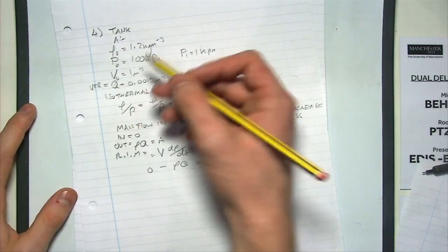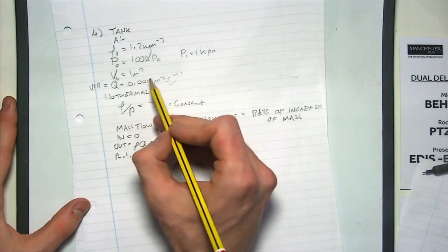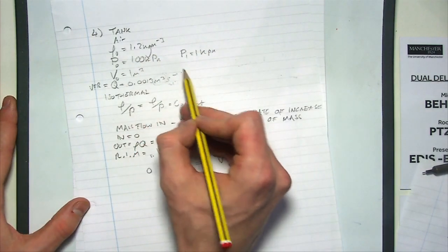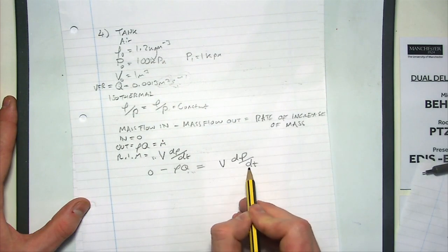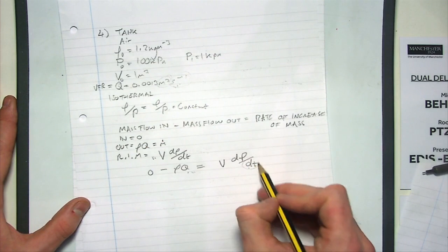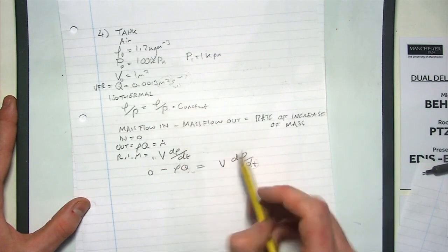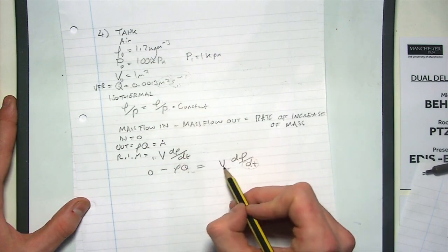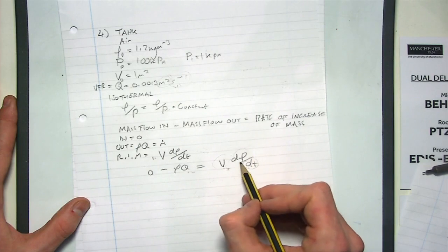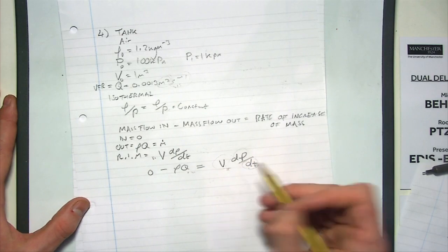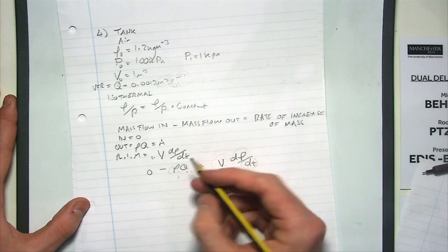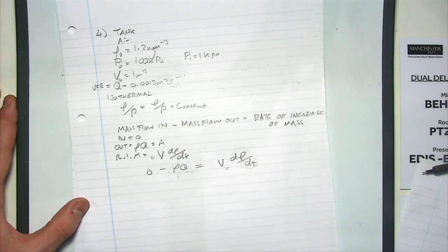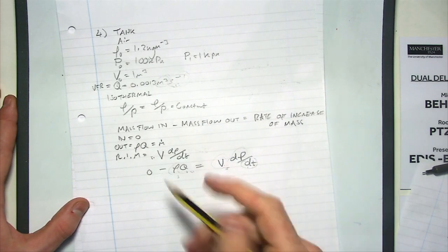But that's what that volumetric flow rate is. It's amount of volume per time. Look at the units. This has time in it, and this is with respect to time, and therefore it gets the time units in it. And because this is underneath, that gives us an s^-1 as well. So you can see how these balance. If you times the volume by this, you're left with kilograms, and if you do this times this, you get kilograms left over in the units as well. I think that's right. Kilograms per second.